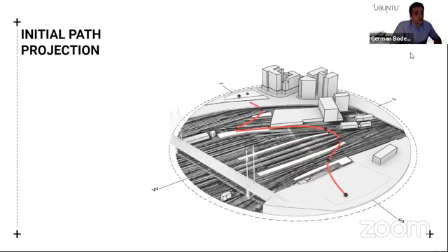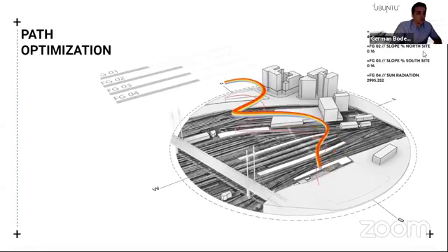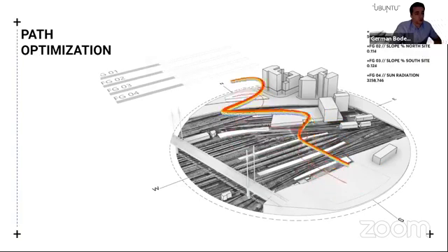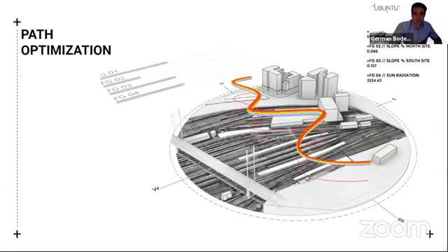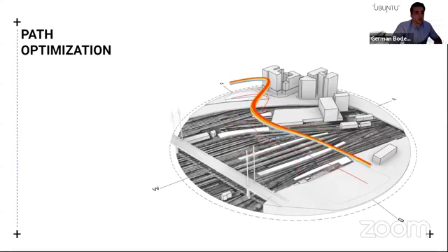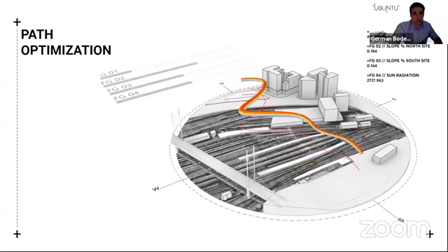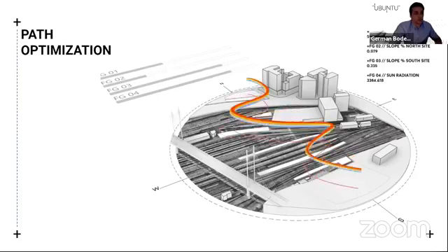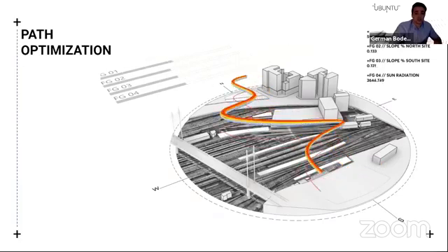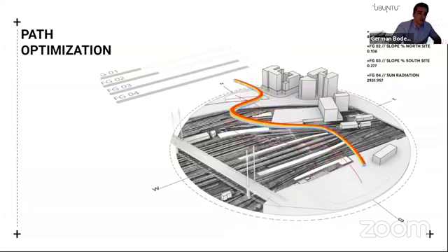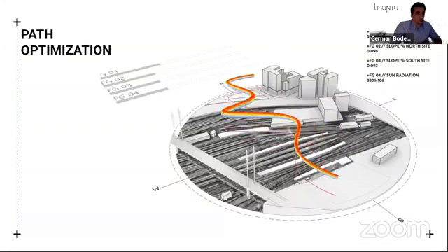We then did a very first attempt to create a path connection between them. So we did a very first selection of points, one from each side, and this gives us this very first meander that connects A to B. We then fit this line principle into a genetic optimization algorithm that consists of 4 different goals. The very first goal is trying to measure and reduce as much as we can the travel distance between the 2 points. The second and third one measure both slope of entry and exit of the bridge in order to create a wheelchair and pedestrian-friendly approach. And then a fourth goal measures radiation in order to try to reduce the amount of sun that this bridge is exposed to, in order to create a more comfortable experience as we walk through it.